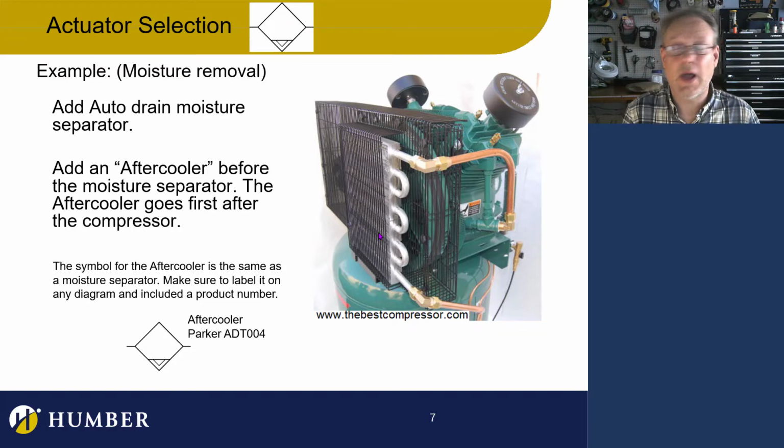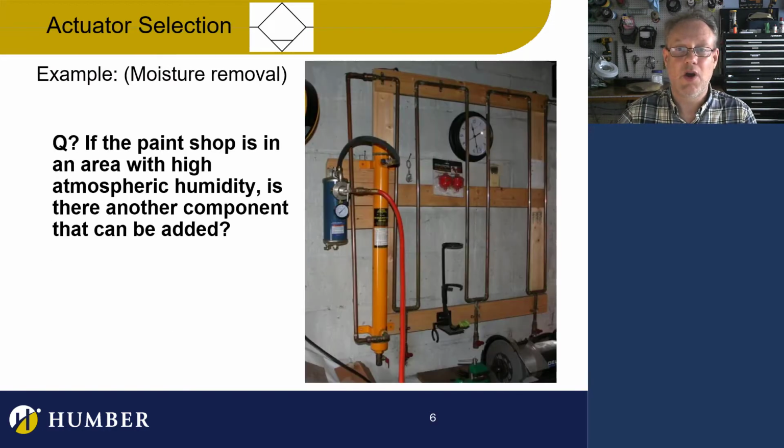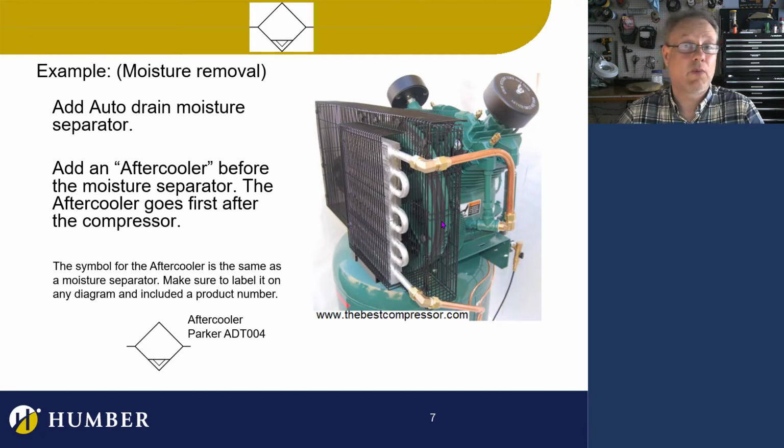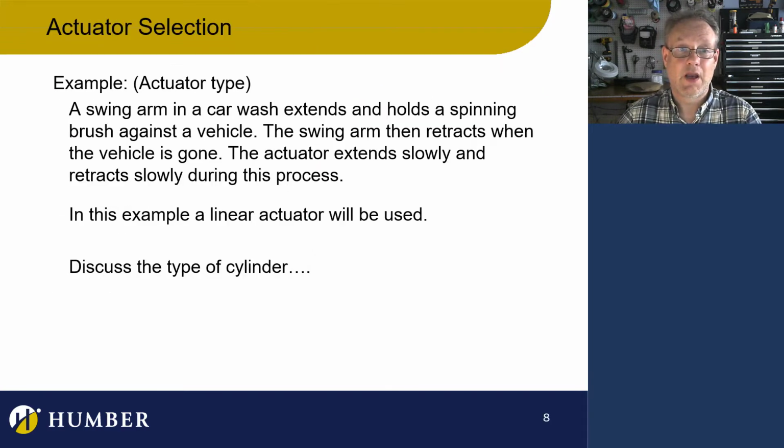And as soon as you cool air down, all the moisture just leaves. So an aftercooler is something we would use for a really damp environment. If you had a paint shop, you might want to put an aftercooler in as well, because then you wouldn't have to go into all of this extensive work. But this is a lot cheaper than an aftercooler. But you might even want to use both. I'd put an aftercooler in a situation where it was actually really humid in the environment. So here we go.